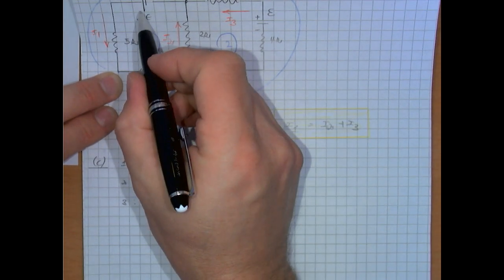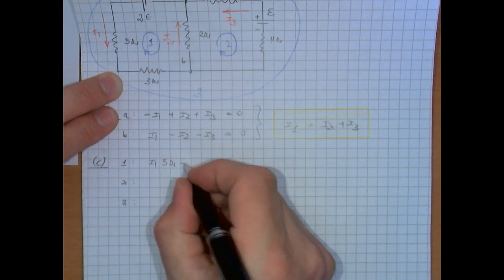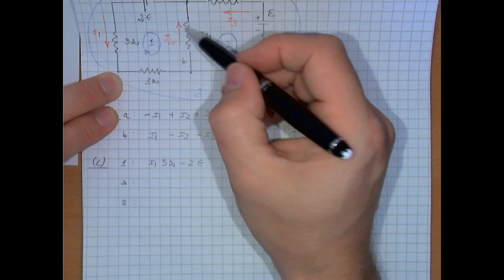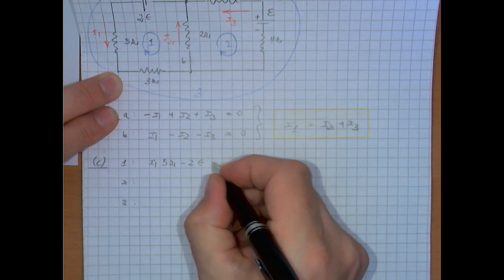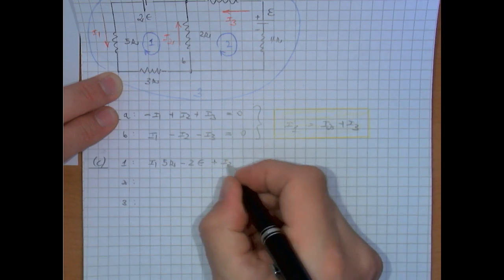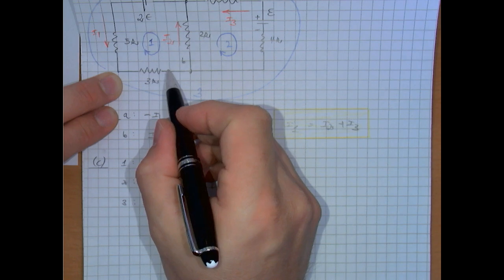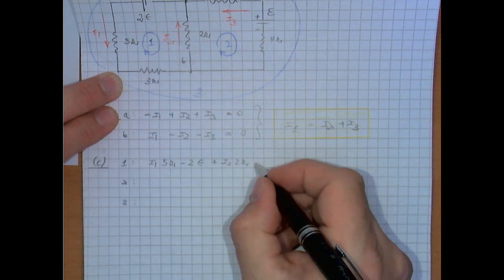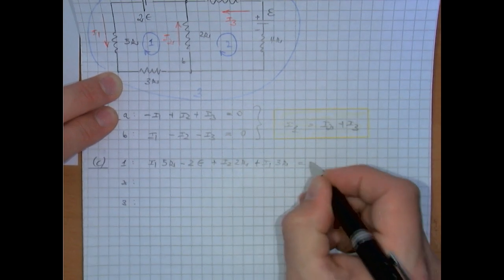We're walking now through the battery from plus to minus, so this would be negative, from a higher to a lower potential, minus epsilon. And then we're crossing the resistor 2R in the opposite direction, so we have here plus I2 2R. And then we have the same thing in the opposite direction for current I3 relative to resistor 3R. We have then plus I1 3R equals 0.